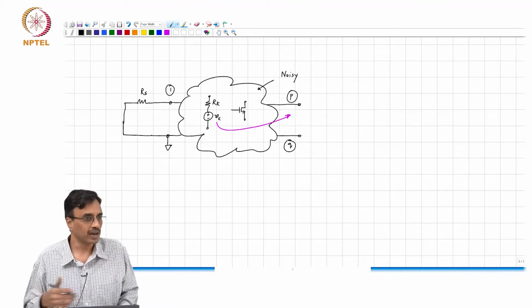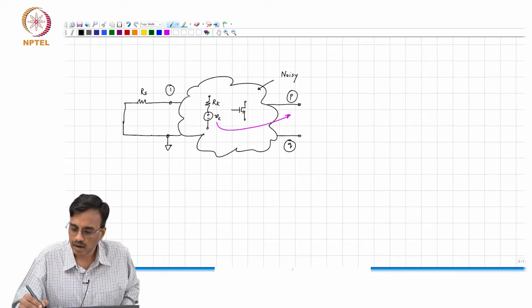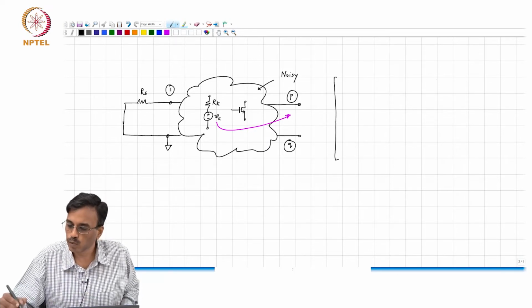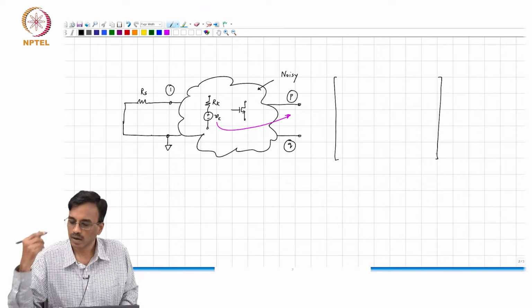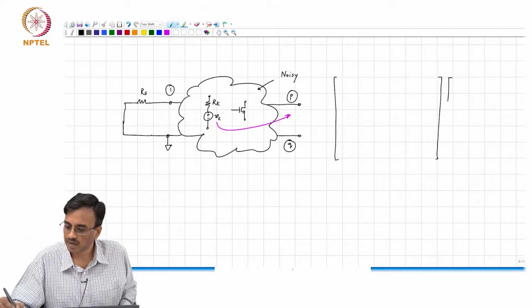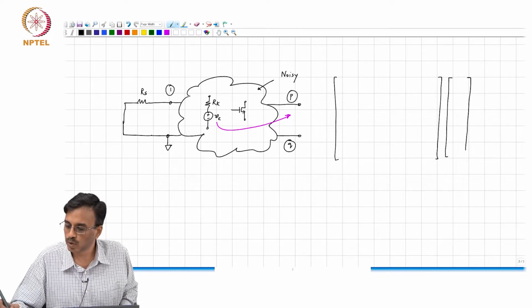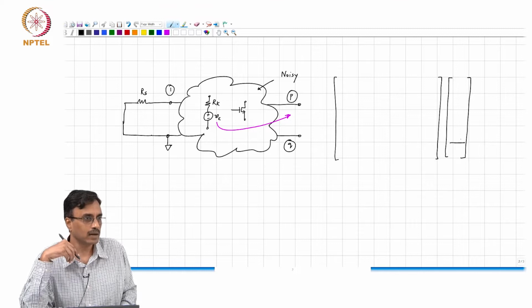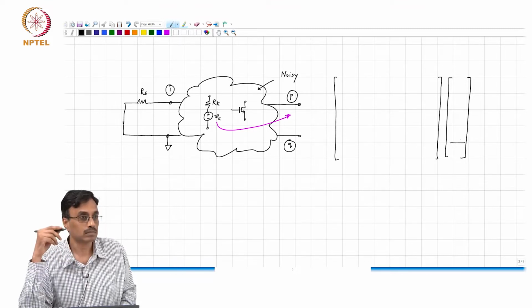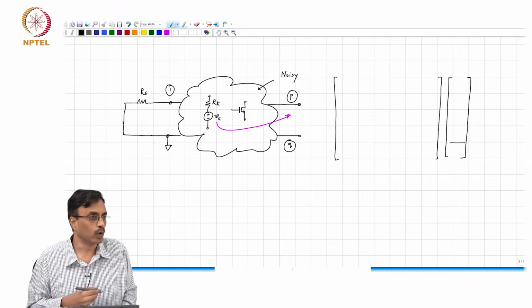and we write the nodal equations as we are used to, and there is only one source here, right. And so, if we write the nodal equations, what do we get? We get the MNA matrix. We know how to do this, right, and the unknowns will be all the node voltages, and well, there is only one voltage source.